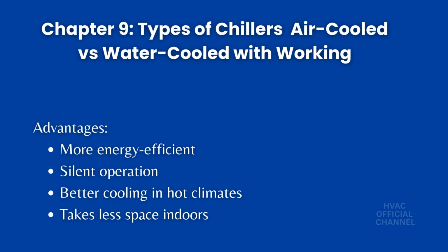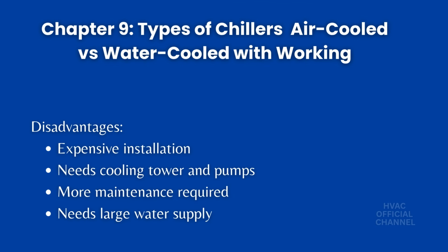Advantages: more energy efficient, silent operation, better cooling in hot climates, takes less space indoors. Disadvantages: expensive installation, needs cooling tower and pumps, more maintenance required, needs large water supply.